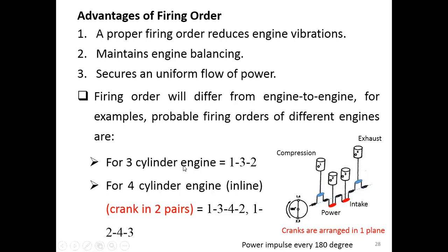For the 3-cylinder engine, when the explosion happens in the first cylinder, the next explosion will happen in the 3rd cylinder, and the last explosion will happen in the 2nd cylinder. So the sequence of the firing order will go like this: 1, 3, 2, 1, 3, 2. This is for the 3-cylinder engine.